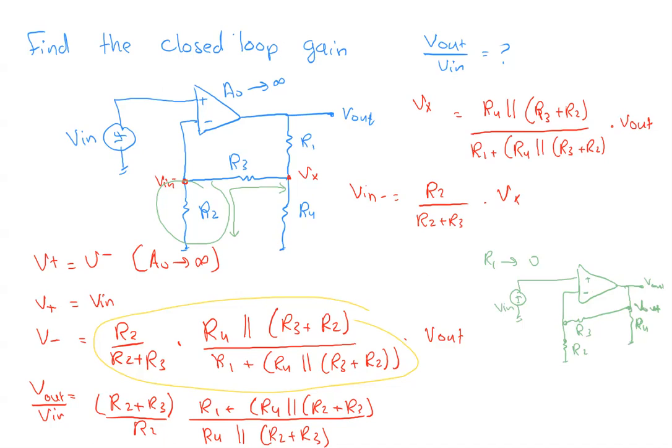So we will just have a simple non-inverting amplifier with the gain equal Vout over Vn. Again, you can derive it very easily with this voltage divider feedback, just from Vout to reach here to Vn negative. And we will get Vout over Vn equal to (R2 plus R3) over R2, and this gets simplified to 1 plus R3 over R2. Just a conventional non-inverting amplifier.